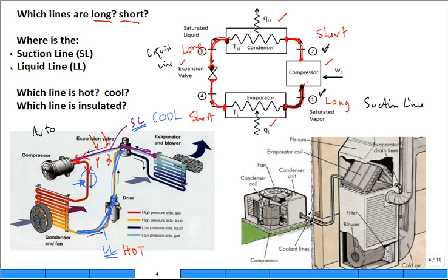And then, so here you can't really see this discharge line. It's so close from the compressor to that condenser coil. But you have two lines, the thinner liquid line and the larger diameter suction line. And one will typically have a big black foam insulation wrapped around it. One will be bare, right? The suction line will have that big foam insulation around it.